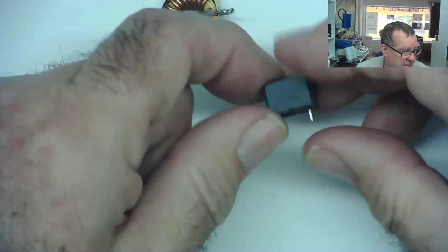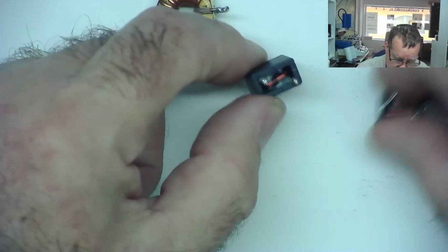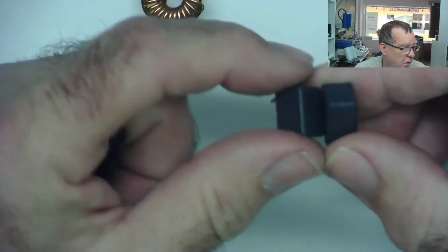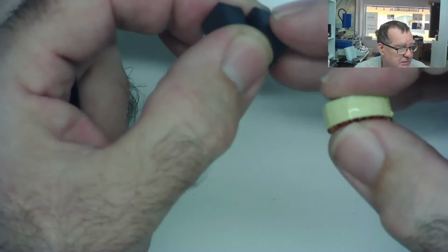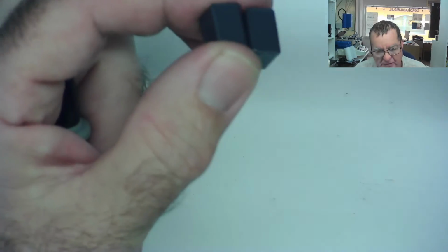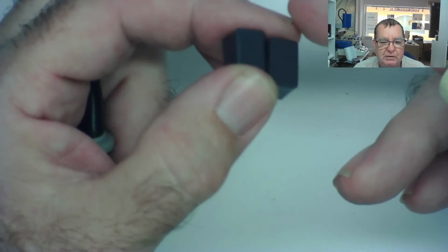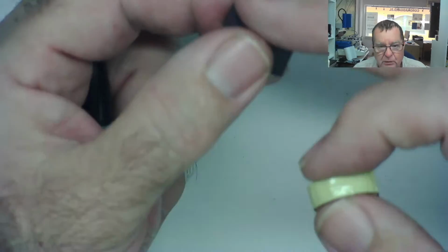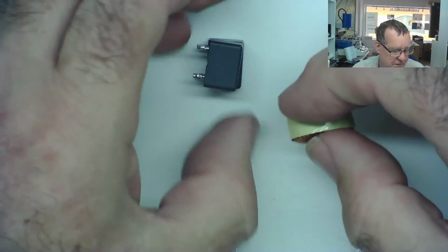The other thing is, in these sort of inductors, you'll find them in VRM circuits. Yeah, another one here. If these are running very hot, but the voltage regulator is working, but the inductors are getting hot, and sometimes they look like these, that is normally because the capacitors on the output side of the coil, the low voltage side, have gone high ESR, and it causes a lot of spikes. So if you find inductors and voltage regulator modules running hot, it's not the inductor, it's the capacitor or capacitors on the load side that are faulty.